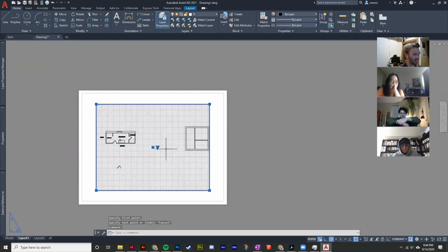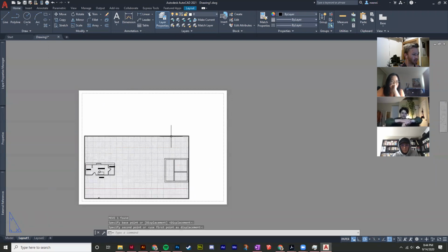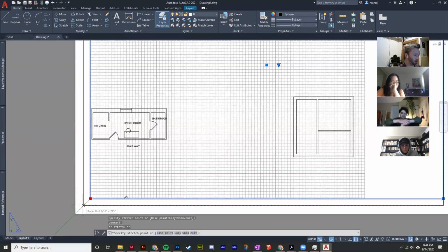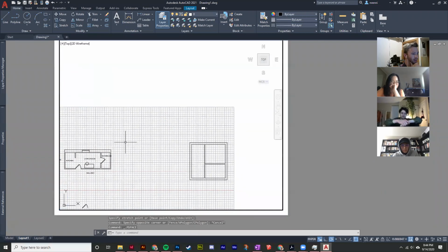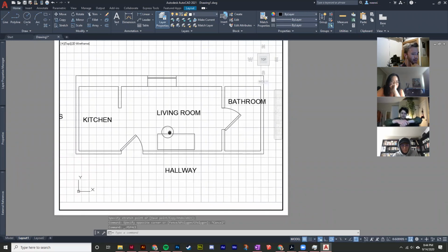And then the box containing your drawing is called the viewport. So this viewport you can shrink, you can move it just like lines or any object. So I'll just make this almost as big as the paper. I'll leave a little bit of margin. And then, excuse me, if you double click, you can pan around inside and make this different scales.